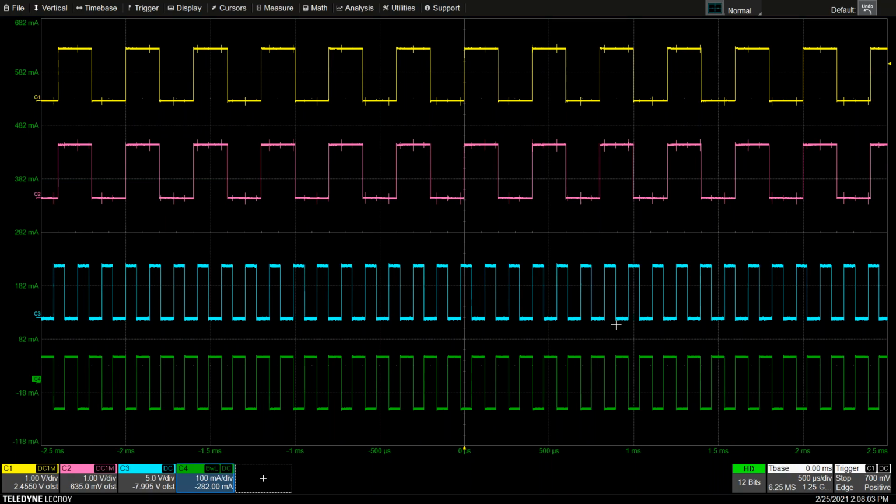We reduced the amplitude to say 1/4 of the size. So we can't have the waveforms overlapped. So therefore, we reduce the amplitude. Well, what does that really mean? In this case, from the bottom of the display to the top, there are 4,000 quantization levels in this 12-bit scope. 8-bit scopes, 2 to the 8th would be 256 quantization levels. So as we take a sample, we digitize it, and we create a digital value for it, put it into memory, and do that at the sample rate of the scope. Then we build up these waveforms.